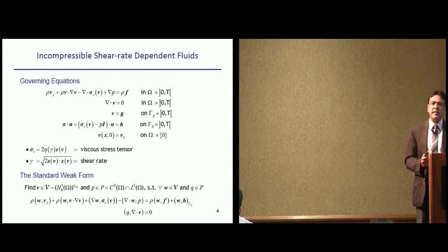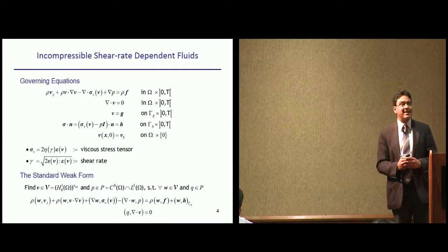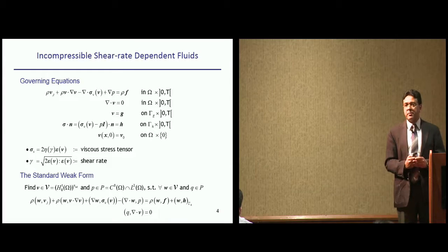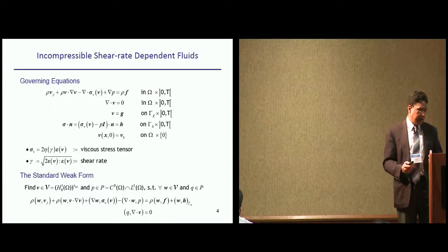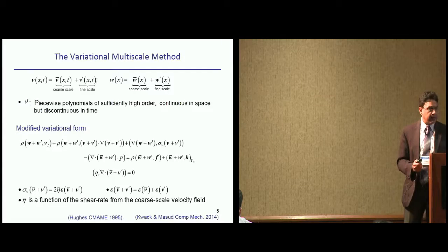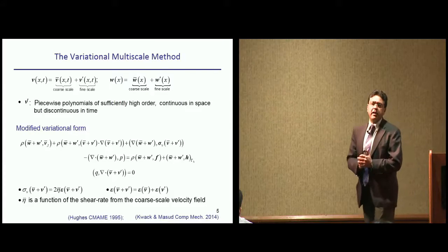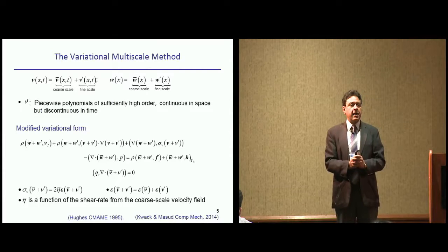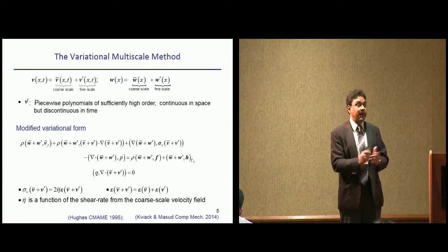Now, there are different techniques that have been proposed in the literature to address this kind of problem. However, I will talk about some techniques that we have developed at University of Illinois, and also highlight the role that Blue Waters has played for us to develop these methods. Any numerical method, finite difference, finite volume, finite elements, any method, as we make a mesh, as we discretize the domain, the mesh starts behaving like a filter.